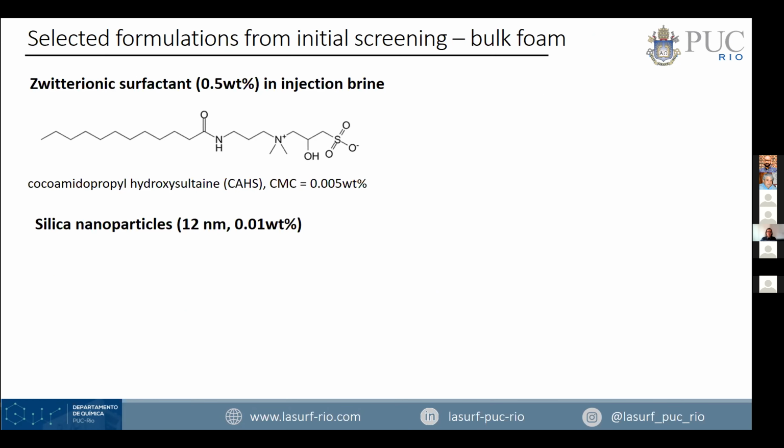I'm going to talk here about only one surfactant. We have screened more than 50 surfactants in our labs. In this case, it's an ionic surfactant that is stable in injection brine, and we use it at a relatively low concentration. It's 0.5% weight, which is okay for foaming because it's above its CMC.